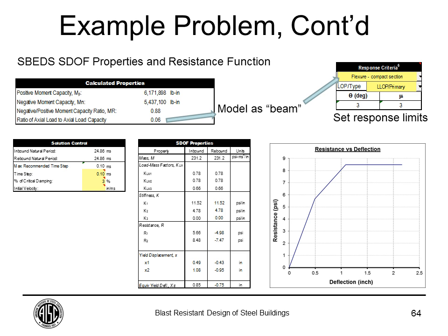Next, with the information that was entered, SBEDS will calculate the moment capacity, and the difference between the positive and negative moment capacity because of the unbraced length. It takes that into account, and it also calculates the ratio of the axial load to the capacity. As you can see, we're clearly under the 20%. So our flexural assumption was right.